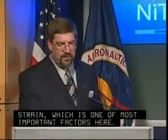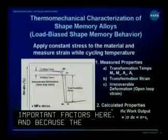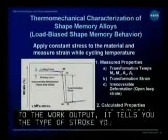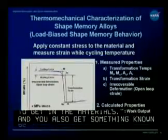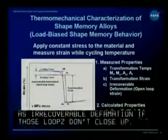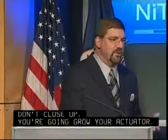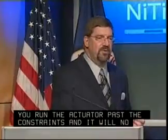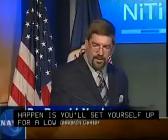And because the transformation strain is directly proportional to the work output, it also tells you the type of stroke you're going to get in the materials. And you also get something known as irrecoverable deformation if those loops don't close up. Now that's a bad thing if the loops don't close up, because what will happen is with continued cycling, you're going to grow your actuator, and if you have very tight constraints, you're going to run the actuator past those constraints and it'll no longer work. Or worse yet, you're going to set yourself up for a low cycle fatigue condition, and the sample will fail relatively quickly.